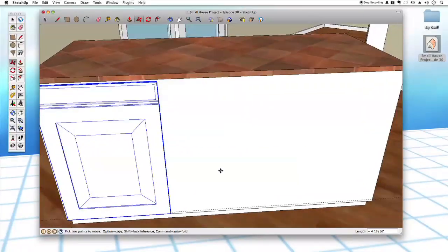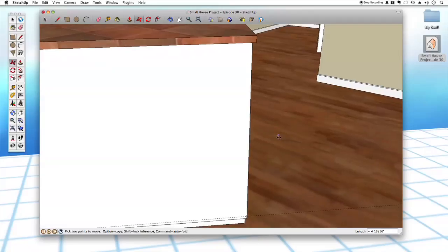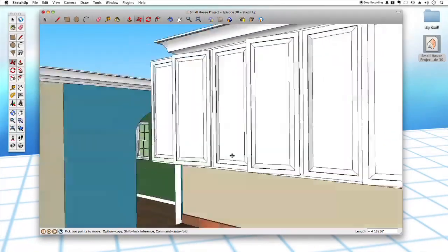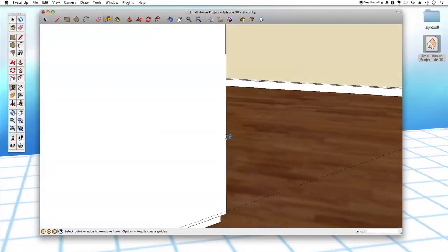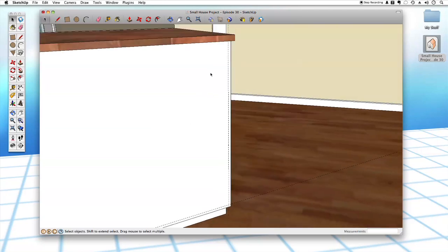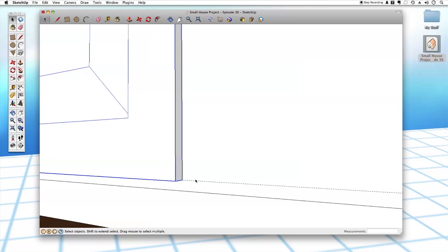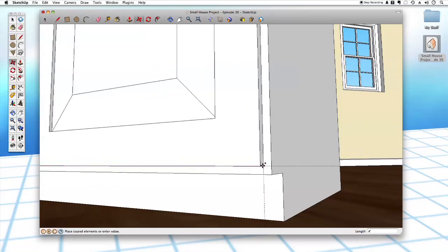And then we just need another one. I'll show you how we can use the divide function. We just did the multiply function with these cabinet units up here. I'm going to show you how you can use the divide function over here. I'm going to draw another 1/2 inch guide right there. So that's where we want the far cabinet to be. So I'll just use the move tool, hit the option key, and drag over another copy of these drawers right there.